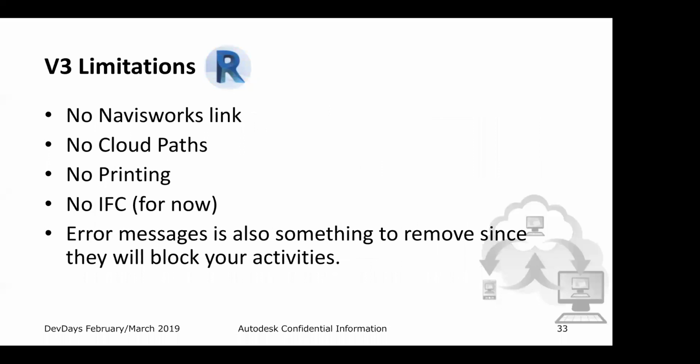About Revit, we don't have support yet for Navisworks links. We don't support cloud paths, printing, and IFC. That's something that we're still working on. And of course, as with the others, we have to handle the error messages and warnings. Let's say you are removing a wall that you cannot remove, and there is a warning there, you have to use the Failure API to handle those problems.